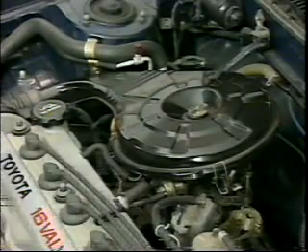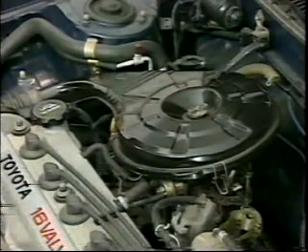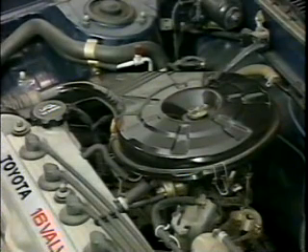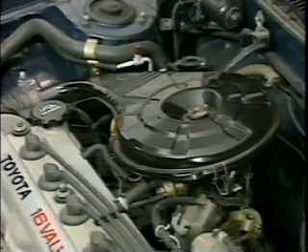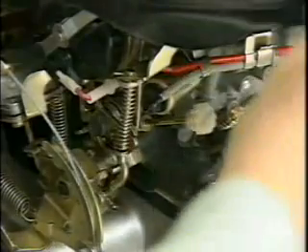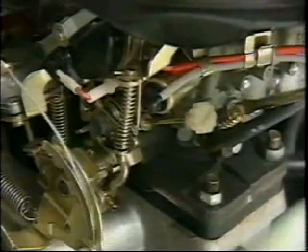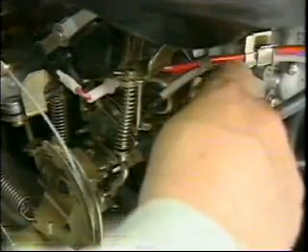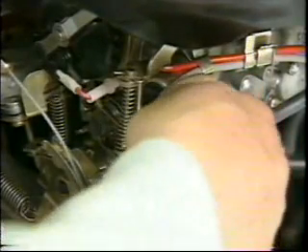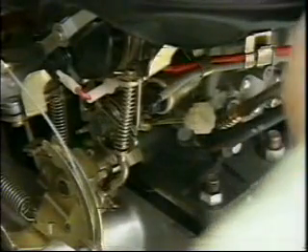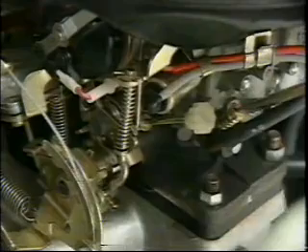Remember that the test must be done with the air cleaner in place. In some models with an air suction system, you remove the air suction vacuum hose and plug it with a hose plug. Turn the idle mixture adjusting screw to raise the engine RPM to its highest permissible idle setting. Then turn the idle speed adjusting screw to set the idle to the specified idle mix speed. Repeat these 2 steps until the engine RPM will no longer go above the highest permissible idle setting.